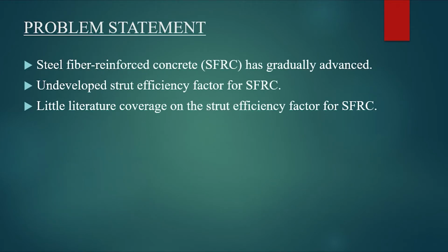Steel fiber reinforced concrete has gradually advanced from a new, rather unproven material to one which now attains widespread use in numerous engineering applications. Although there are many design codes that propose the strut efficiency factor for conventional concrete, a common model with a standardized strut efficiency factor for steel fiber reinforced concrete has not been achieved due to little literature coverage. Hence, it will be a significant contribution to develop a strut efficiency factor to design SFRC beams.